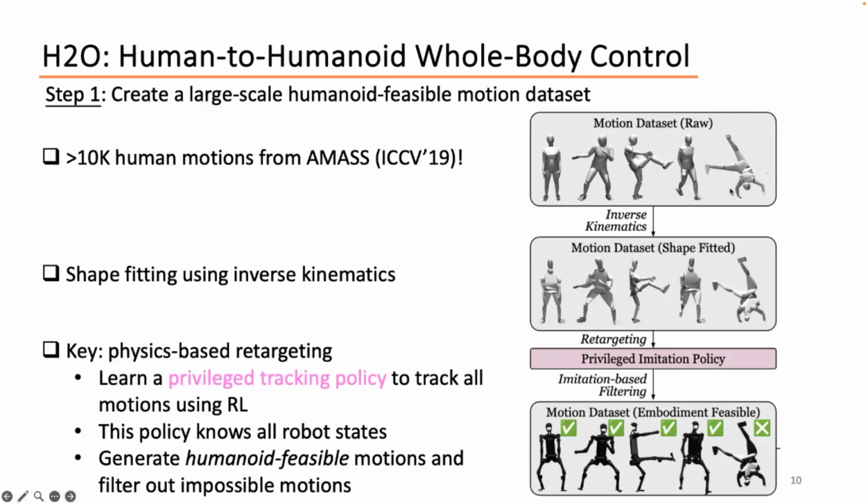So this part actually makes the policy look natural and close to human. The difference from BC is that for BC, we directly learn the action, the A, right? But here we cannot, because we don't have A from this human motion. We do reinforcement learning, but the goal is to track what the human does. So one is direct behavioral cloning, and this is a kind of indirect tracking.